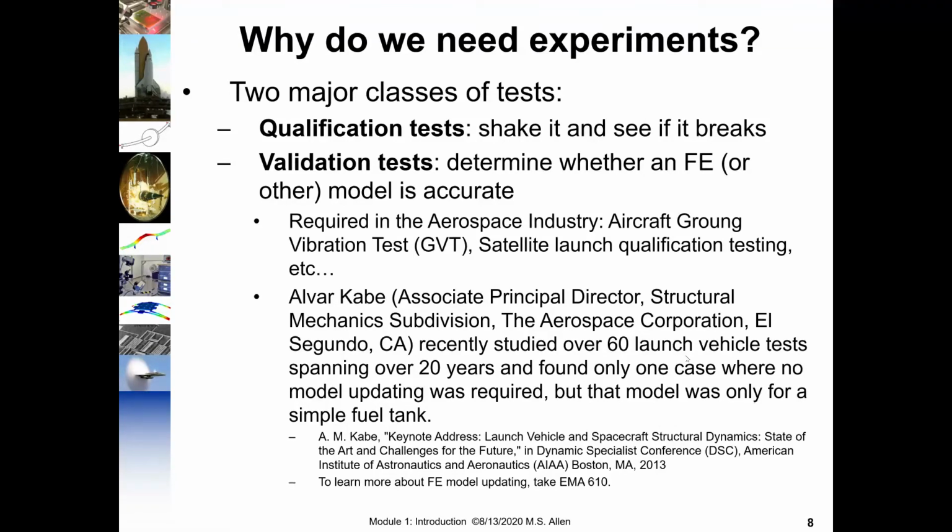There might be materials we're not quite sure of the properties. There might be geometry that we have to approximate to be able to mesh it without requiring too much computational cost. Or there might just be things that are overlooked, brackets that we approximate one way that we find later wasn't necessary. So experience has shown over and over again in the launch industry especially that this testing is critical. And so often it's required, and it's an integral part of the design of the vehicle.